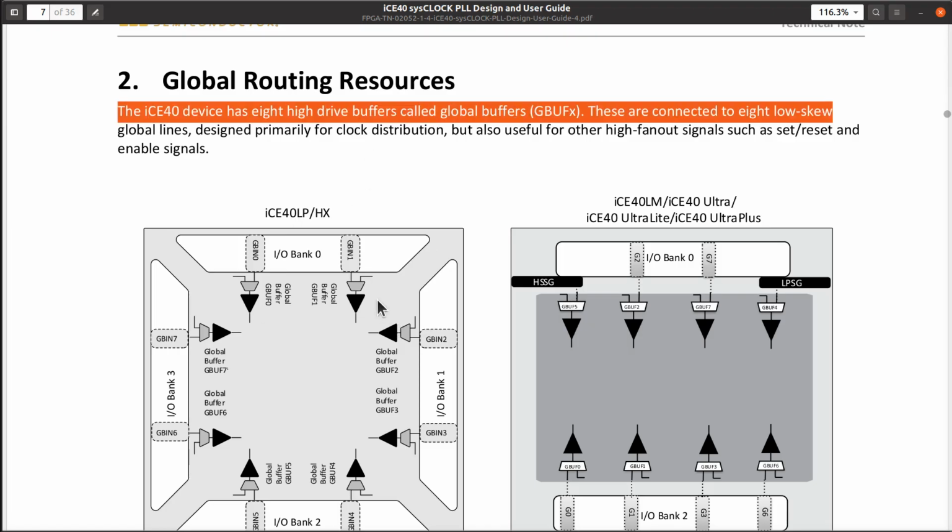buffer, which means that it goes everywhere in the entire FPGA so that any of the LUTs, any of the circuitry that you want to design can easily get access to it with the least amount of latency and skew when you were thinking about the clock arriving at all the different circuits inside here, the thousands of LUTs in there. You do not want the clock to be going up and down at a different time for one LUT versus another LUT. It can be very, very bad and inconsistent and difficult to debug your circuit if that happens.